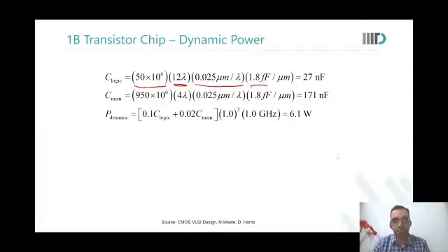So what is this 0.1 and 0.02 in this calculation? What were we talking about when we introduced the subject? The activity factor, the number of togglings to expect. So 0.1 and 0.02 are the toggling factors for logic and memory separately, right? Yes. 0.1 is the activity factor for the logic, and 0.02 is the activity factor for the memory.